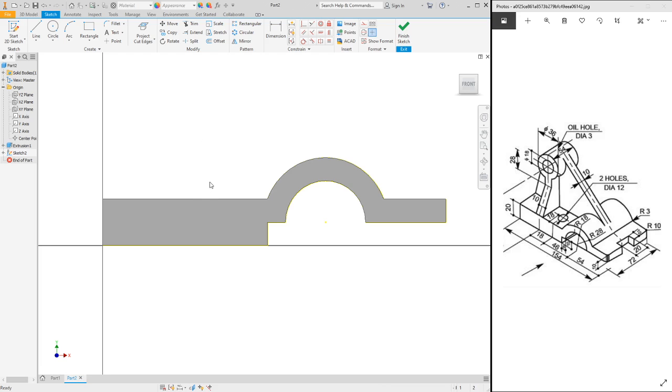So when you use that, right click and you click on slice graphics, it will remove the front portion of the object so that we'll see exactly the surface around where we are doing our next sketch. So you can see the outline is yellow. That is the projected cut edges from the existing model on the working environment.